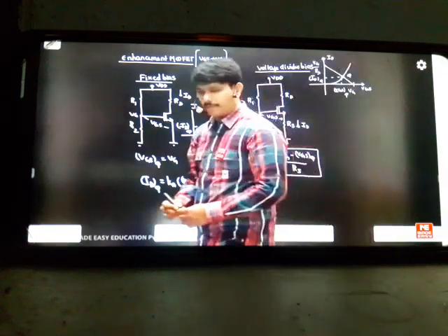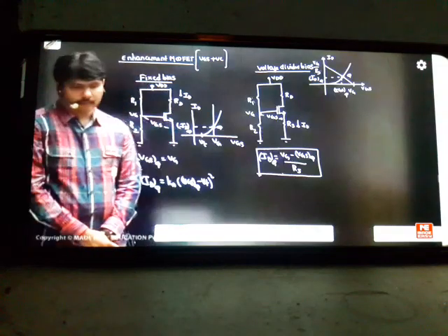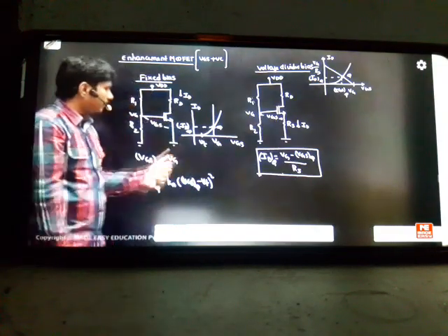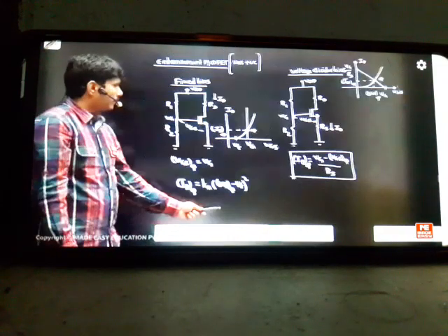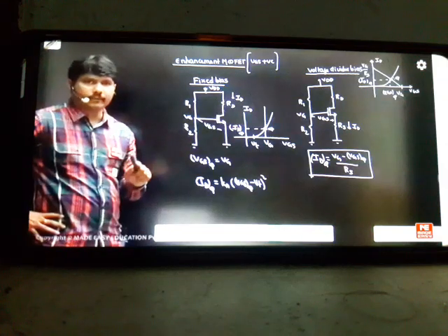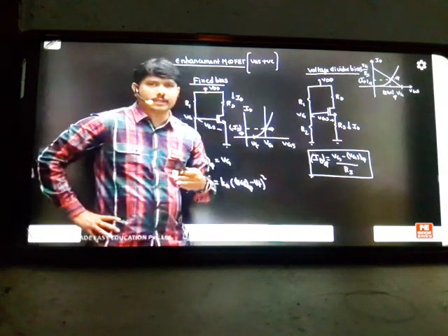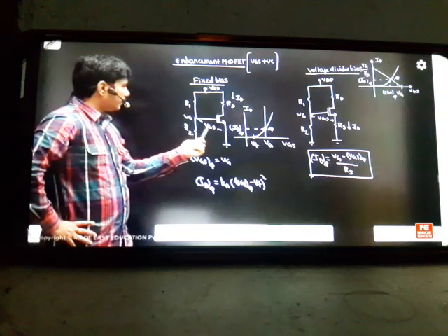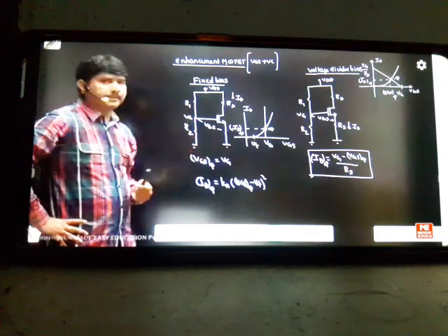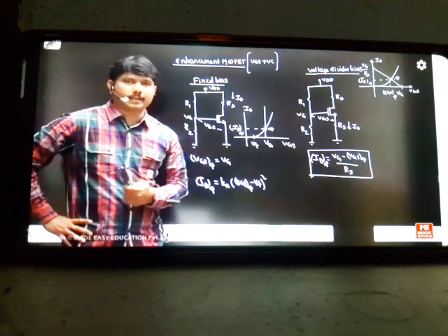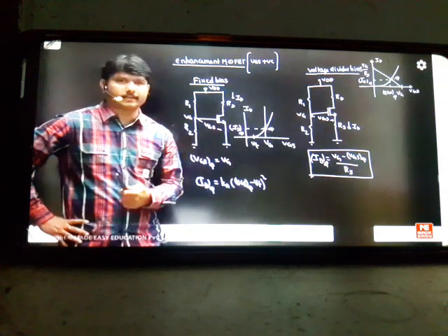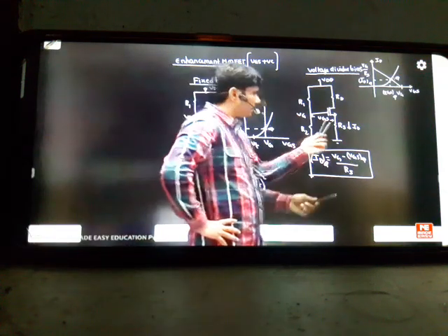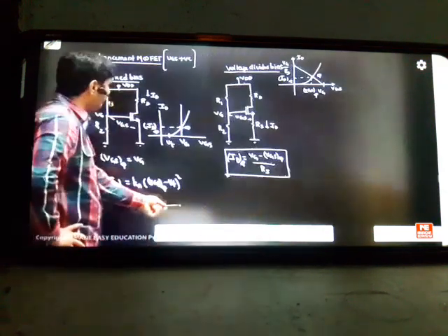So this is the technique we follow, the voltage divider biasing technique. Sumanta, please remember one logic here. Whatever we are seeing in the previous circuit is not voltage divider biasing. Voltage divider biasing is fulfilled only if there is RS, that is self bias also added to the voltage divider bias. Then only we can call it voltage divider biasing. But earlier you only made the voltage divider and did not include RS, so VGS became equal to VG. That is called fixed biasing. You see a divider, but it is a fixed bias circuit, because you are fixing the voltage there. Voltage divider means RS should be included. That is the difference between these two circuits.